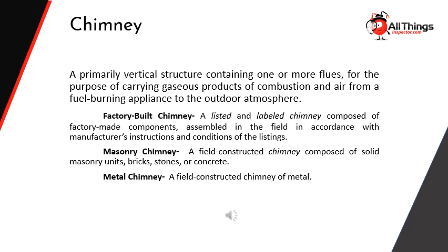Chimney. A primarily vertical structure containing one or more flues for the purpose of carrying gaseous products of combustion and air from a fuel-burning appliance to the outdoor atmosphere. Factory-built chimney. A listed and labeled chimney composed of factory-made components, assembled in the field in accordance with manufacturer's instructions and conditions of the listing. Masonry chimney. A field-constructed chimney composed of solid masonry units, bricks, stones, or concrete. Metal chimney. A field-constructed chimney of metal.